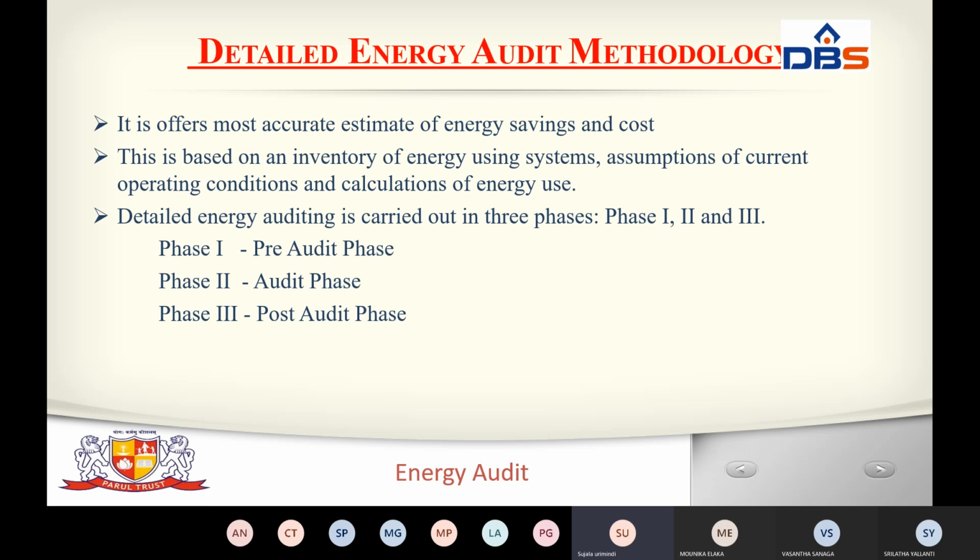What is the benchmark audit? The benchmark audit is an analysis consisting of a preliminary whole building energy use analysis based on use and cost, comparing the performance of the building to those of similar buildings. What is a walk-through audit? Its main inspection is based on visual verification and study of the installed equipment and operating data, along with detailed analysis of recorded energy consumption collected during the benchmark phase. This is the preliminary audit, the level 1 audit, the walk-through audit.